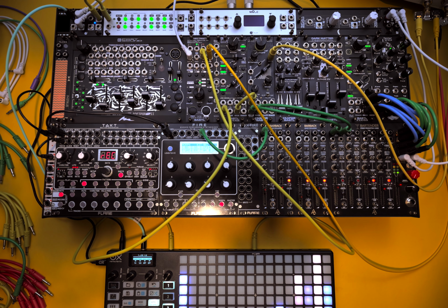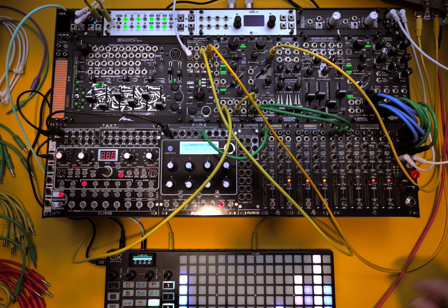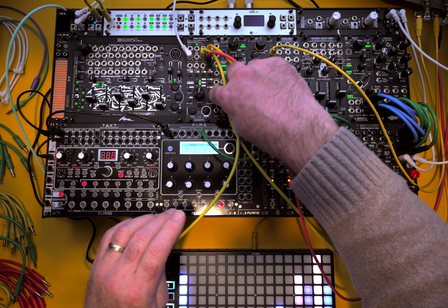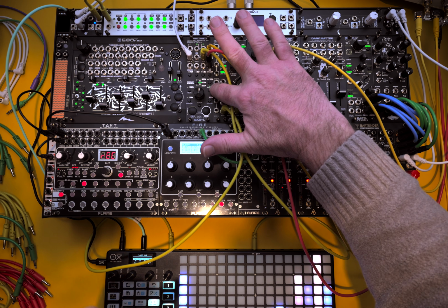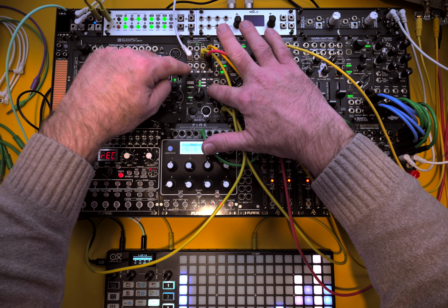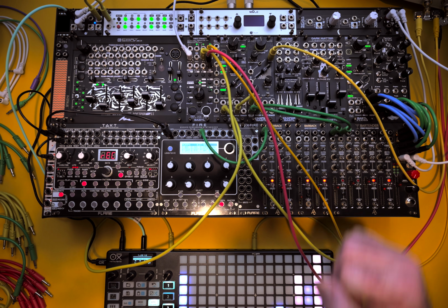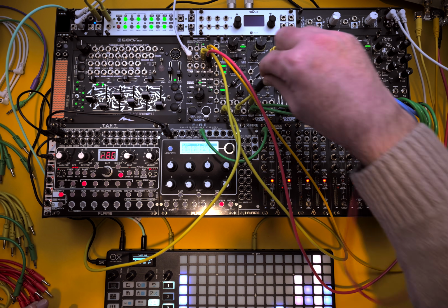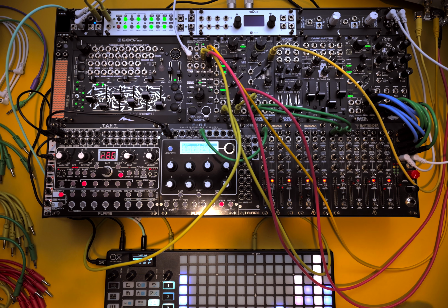Let's try another envelope. This time we'll patch it into maybe the FM index. We'll use the pink channel, so channel 2 here on the oscilloscope. So I'll go to envelope output F, go to channel F, so I press F to select it. We go into envelope mode, press and hold F, so I cycle to the envelope trigger mode set, which means input F is now going to accept a trigger. We'll patch the envelope into FM index here on Ikarie, on Pizza.